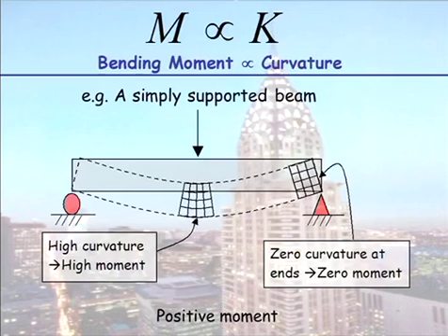So I have here my simply supported beam, and I put a point load in the middle. And if you do look at the grids on here, when I say something's curving, what I mean is that square grid now starts looking like that, okay? It's getting smaller at the top and bigger at the bottom. So if you look at this square grid here, and you'll get it to look at it in the tube class, I won't bother passing one of these around now. Can you see any curvature happening here at the support? No, our grid stays as rectangular. So the internal moment in the beam there is 0, which it should be at a pin support.